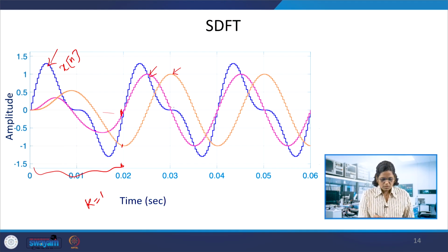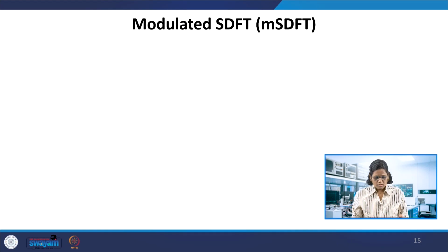So this is just the simple extraction of the original signal. The in-phase component is already there. The quadrature component is actually one more addition of the SDFT. You can get the quadrature component as well if you would like to use it in some other applications. So this is the SDFT output.